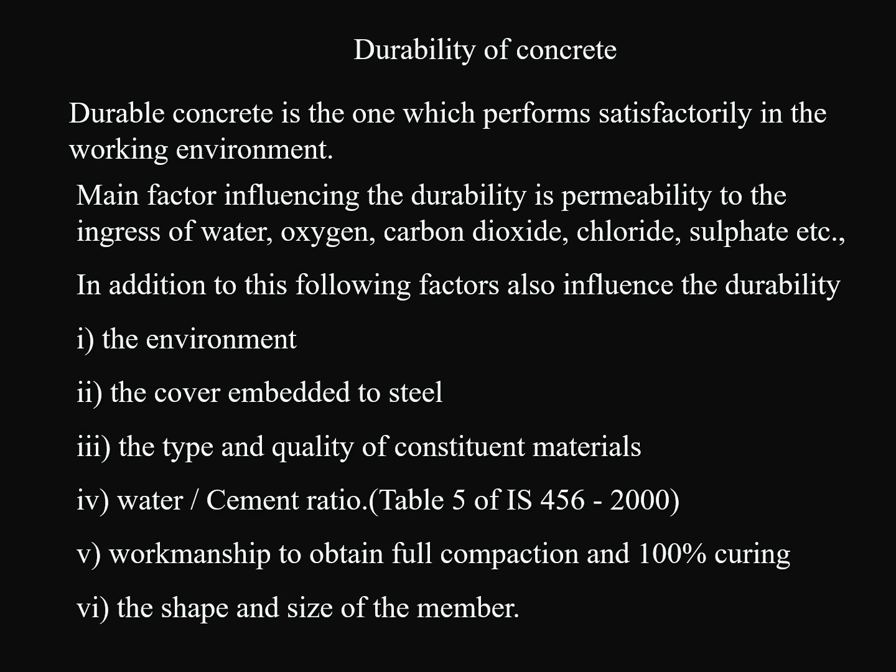They are the environment, the cover embedded to steel, the type and quality of constituent materials, water cement ratio, refer table 5 of IS 456, workmanship to obtain full compaction and 100% curing, the shape and size of the member.